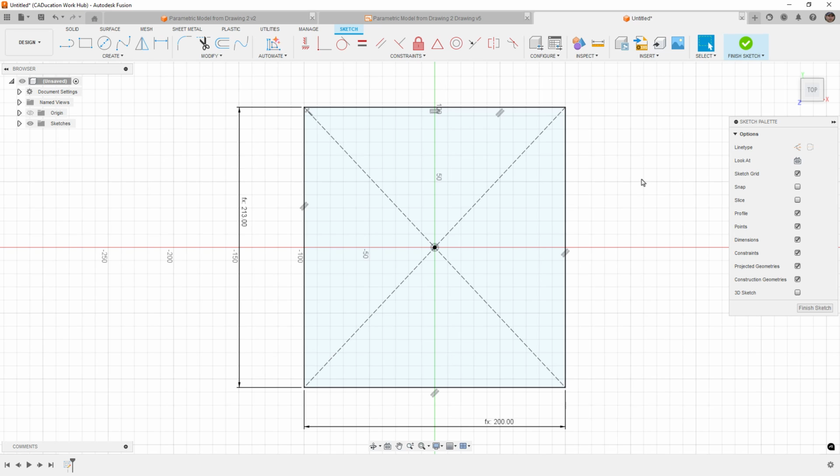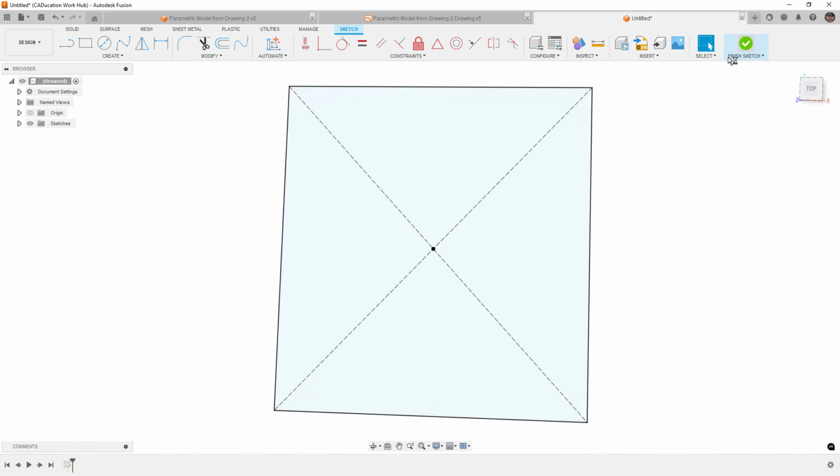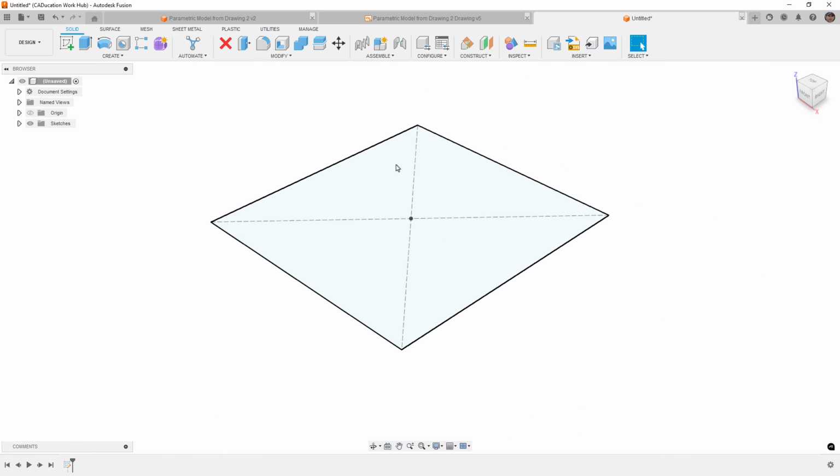In most cases, when you have to go back to a sketch to edit a fillet, you run a higher risk of breaking the sketch. So for example, with the center point rectangle, if we add a fillet to the corner, we are going to get a warning about constraints that are being removed, because these construction lines are no longer hitting the intersection of those outside edges. In general, Fusion has been pretty good about fixing those and applying new constraints, but I prefer to do things at the feature level when possible.